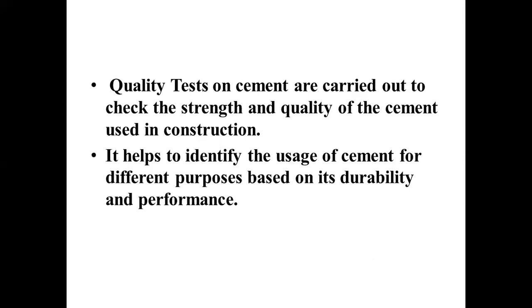It helps to identify the usage of the cement for different purposes based on its durability and performance. One is strength, another is durability, and how it performs and where it has to be used. What are the different types of cements, whether we go for 33, 43 or 53, and where we can use 33, 43 and 53. These performances are identified by the test alone.